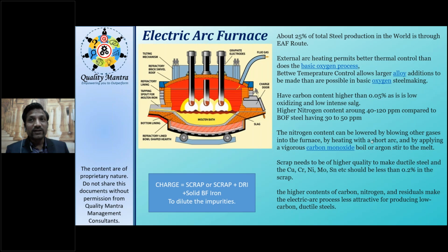When we saw the blast furnace process, there is a molten metal also, and you can convert it to solid, pellets or small ingots. So that can also be used. Another thing, along with DRI it can use HBI also. What is that HBI? DRI in the form of HBI also it can be used. That is hot briquetted iron.